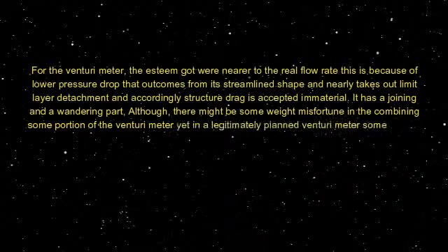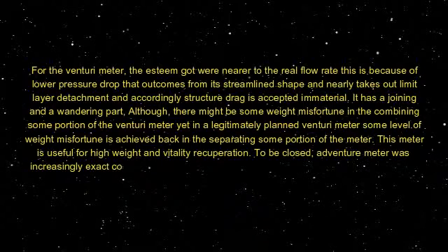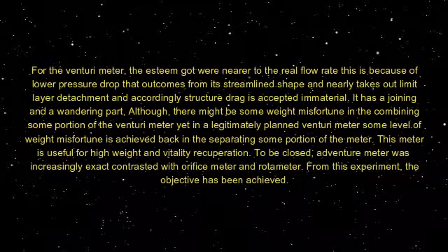For the venturi meter, the values were nearer to the real flow rate. This is because of the lower pressure drop that comes from its streamline shape, which nearly eliminates boundary layer separation, and accordingly structural drag is negligible. It has converging and diverging parts. Although there might be some pressure loss in the diverging part of the venturimeter,